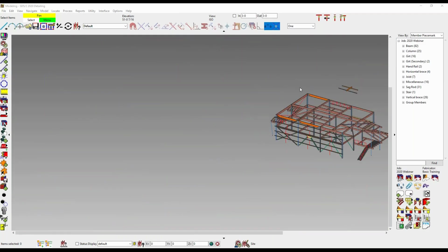So I'm going to go into the model here, and the first thing we're going to cover is for detailing. This is a filter that I can use to filter out specific erection view drawings. Maybe I want those in a separate list. I don't want anybody to mess with those, changing my depth check or doing some of those things that you do while modeling. I want to keep those separate from everything else. We have this tag for detailing.